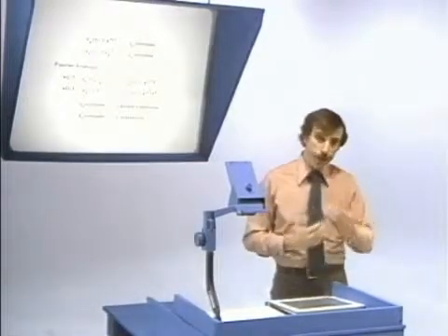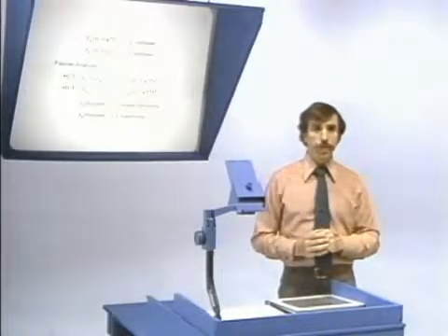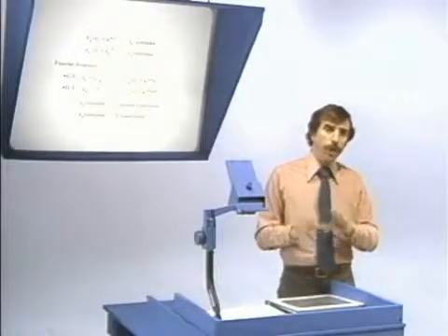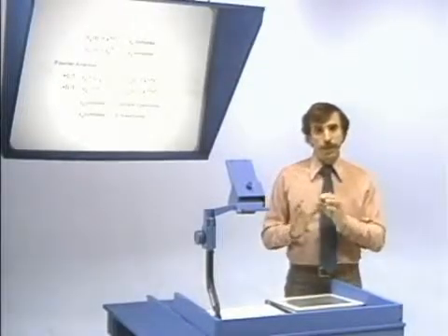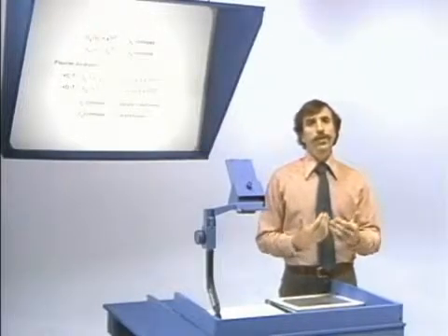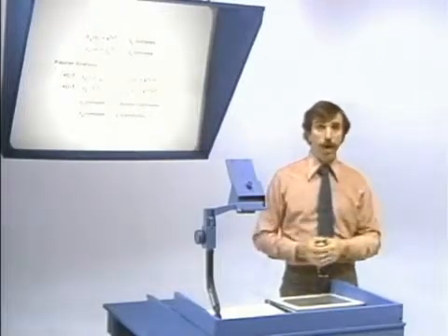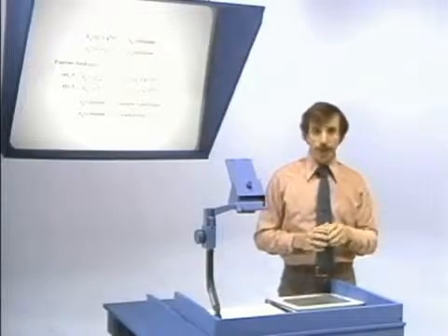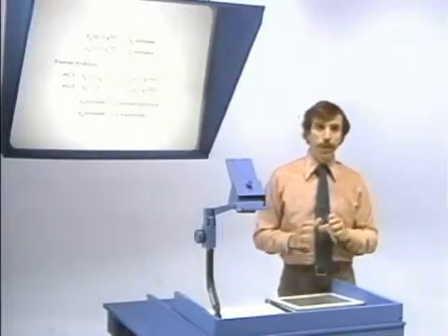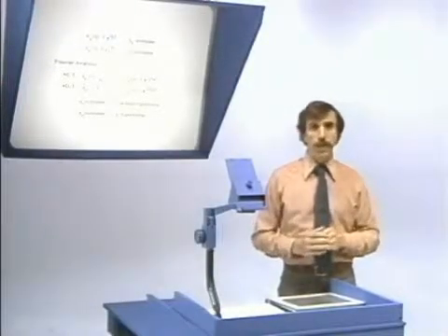What we'll find with complex exponentials, either continuous time or discrete time, is that they very nicely have those two properties. In particular, the notion that the output of a linear time invariant system is easy to compute is tied to what's referred to as the eigenfunction property of complex exponentials, which we'll focus on shortly in a little more detail.